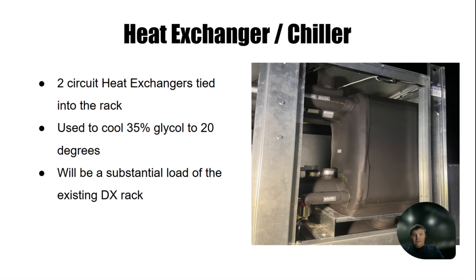Version 1, and version 3 and beyond so far, have liquid line solenoids before the chiller EEVs. Version 2 went away with that for a software solution, but the newer versions have brought that back. And what I've noticed is the open air meat cases seem to struggle a little bit, and chilling the glycol down to 17, 18 degrees seems to take care of that.